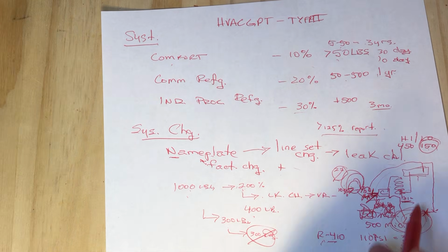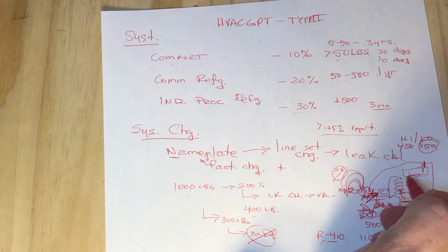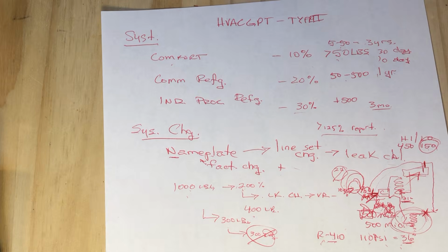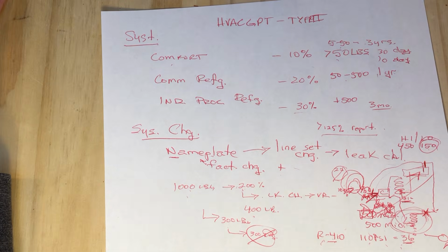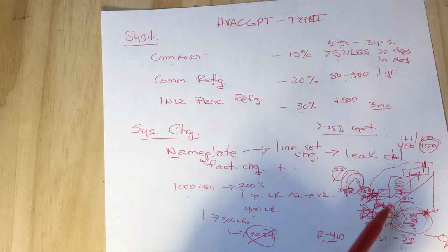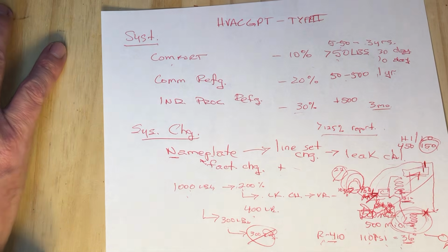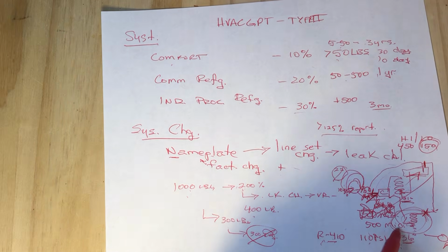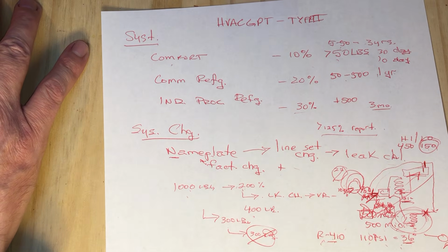Let's say we could pump down, we've got a king valve here, and we don't need to hook up the recovery machine, and we can pump all the refrigerant into the receiver, and then keep this at 0 psi, because this is in pump down mode, so we've isolated half the system. That's a system dependent process for recovery, where you're not using the machine, the active process, you're using more of a passive process, and that would be okay. You'd stop the clock. That's what we were talking about initially when we started drawing this system.